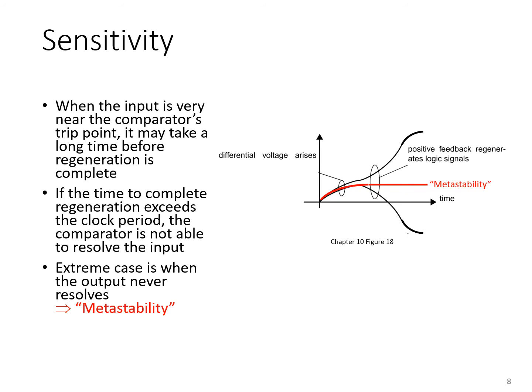Now, a tricky point is exactly how much does the latch have to resolve before we say that it's no longer metastable. Let's look at the black waveforms and let's say this is the end of our regenerative clock phase, and the outputs have reached this level. Has the latch successfully regenerated? Well, what if we had a clock cycle that was a little bit slower and we wait till here? At this point, has the latch regenerated? How are we to say?